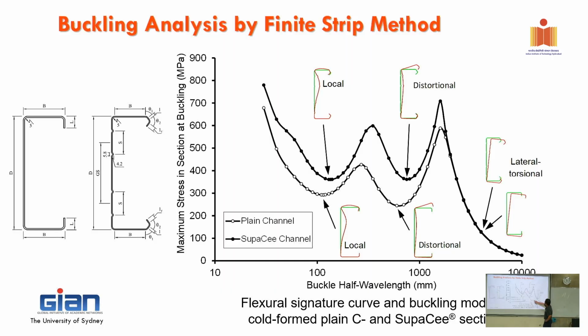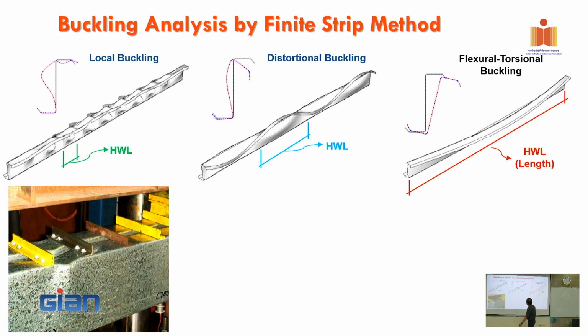So in this case, you can see that it helps sectional capacity, but not really flexure torsional buckling. For flexure torsional buckling, the only way is to provide more lateral strength. But for the sectional capacity, you can make the section as complex as you want. Okay? Get it? Good. So I'm sure that you understand now.